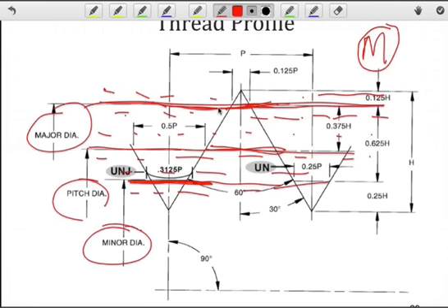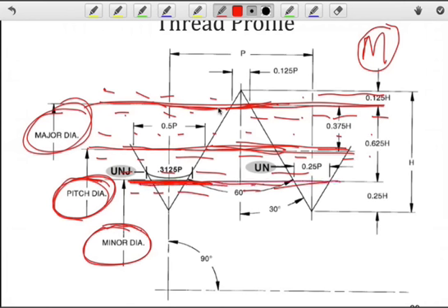Do I use MMC for the minor diameter, MMC for the pitch diameter, MMC for the major diameter? Whichever one you use, and some people might argue for the pitch diameter because that's kind of like using, in a sense, the midplane, but that doesn't guarantee, of course, that your minor diameter and major diameter are controlled. So if you plan on using that M, then of course it should be clear what you're referring to in terms of the thread tolerance.